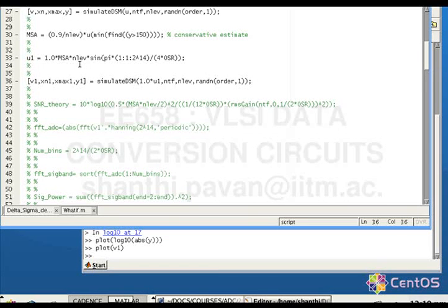The switching threshold must be plus minus 1. If there are 15 levels at the output, 0 must be a level, and then there must be 7 levels on top and 7 levels below. If the quantizer output must have 15 levels, and if you want to make it a symmetric characteristic, then 0 must be a level, and there must be 7 levels on top and 7 levels below, right? I think it's straightforward. This is a 15 level quantizer, yes. No, you can have any number of levels you want, right? This just happens to be 15 levels, that's all.